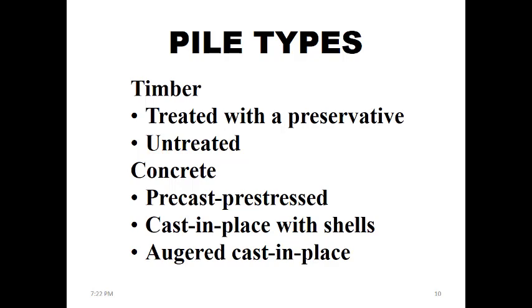In certain situations, you will realize that the bottom part of these cast in place piles can be larger in diameter than the rest of the body of the pile. The reason for that is to increase the surface area that will support the load through the tip of the pile. How will you make a larger excavation underground after drilling it?